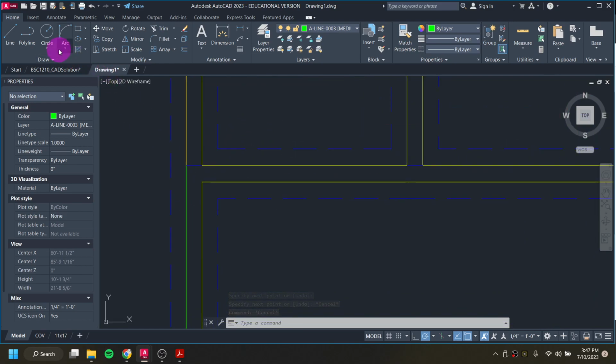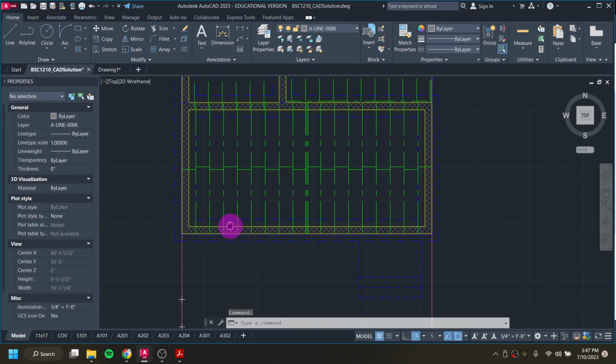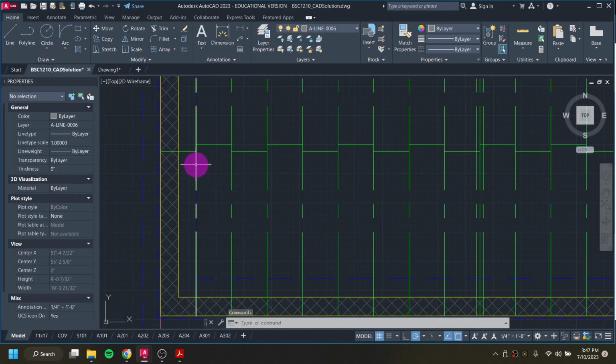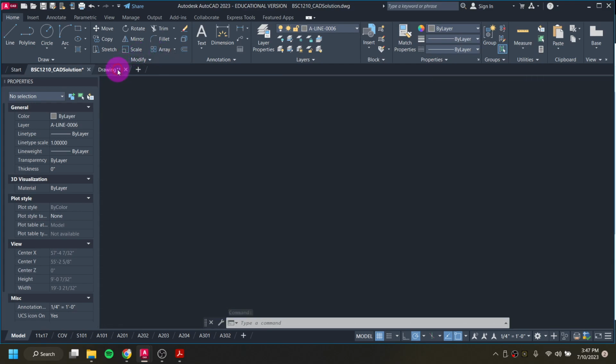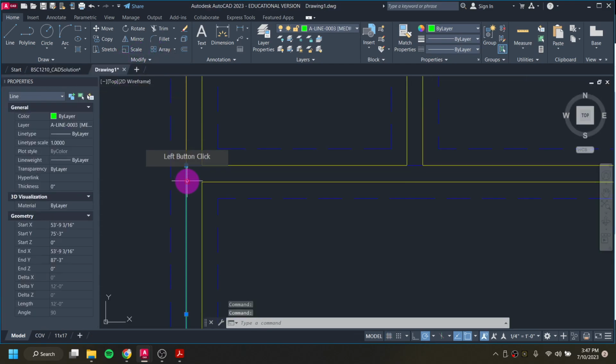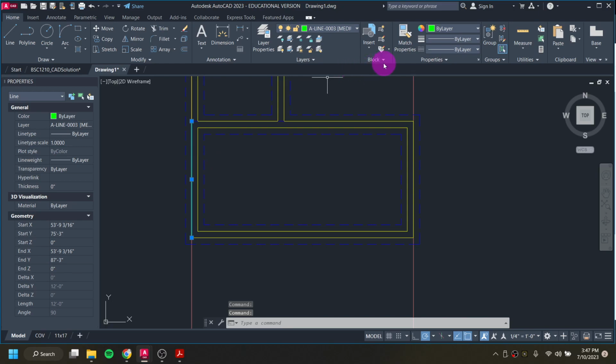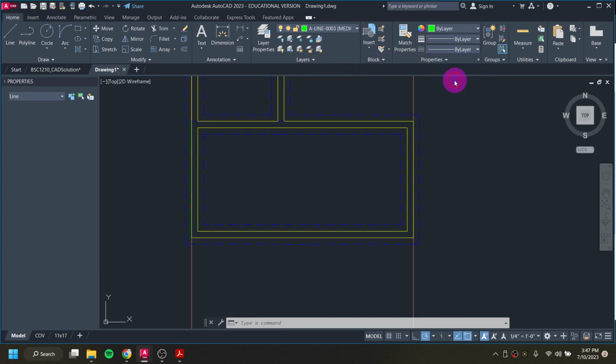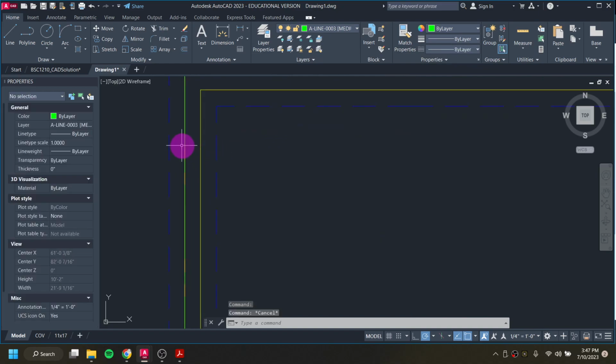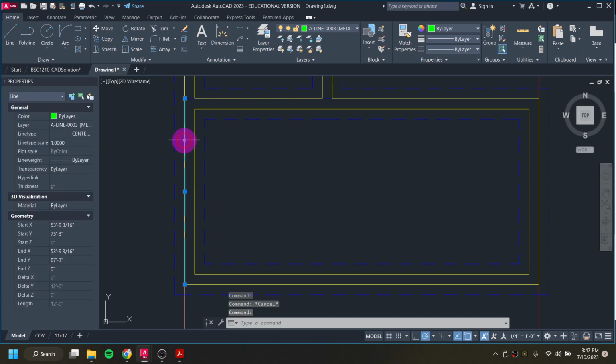Now this is a solid line, and when we're looking at our drawing, we don't want a solid one. We have a center one here. And so I'm going to click on it and do a line type override to make it into a center. And I know this one doesn't even exist in the drawing. It's just more to give me a reference.